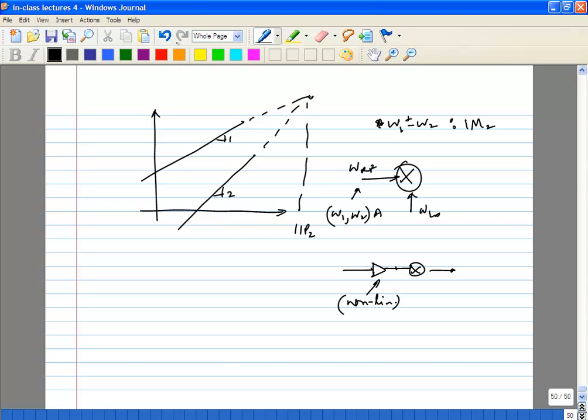Now the reason this is important, in a normal heterodyne system, we saw that we are interested in IIP3 because your 2 omega 1 minus omega 2 and 2 omega 2 minus omega 1 fall directly very close to your signal, right? And then they get mixed down. In this case, because you are looking at a direct conversion receiver in the project, your IM2 components can actually fall in band. So now you are interested in DC. So your omega 1 minus omega 2 term will matter, okay.